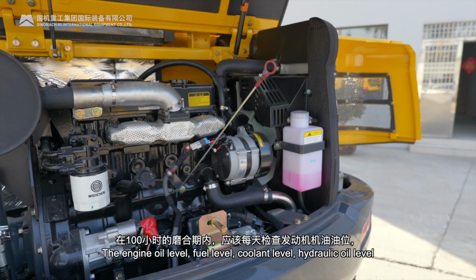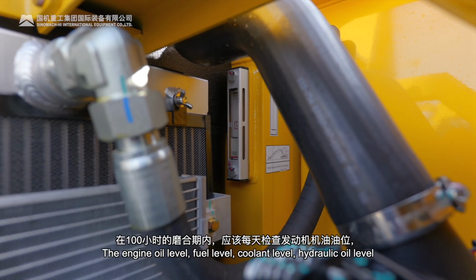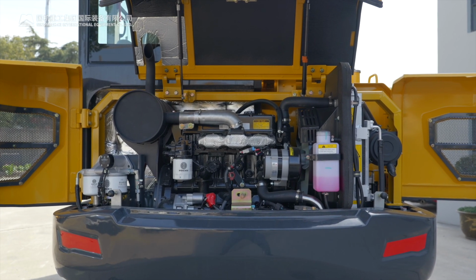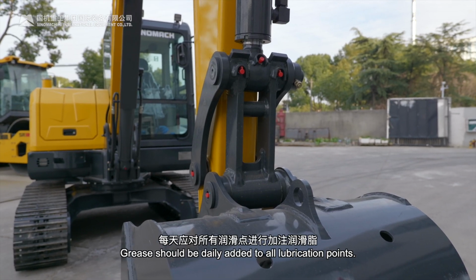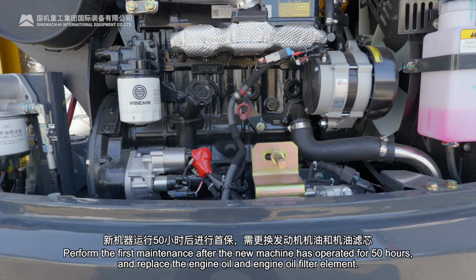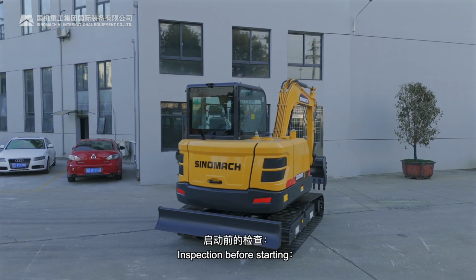The engine oil level, fuel level, coolant level, hydraulic oil level, and leakage situation should be checked daily during the 100-hour run-in period. Grease should be added daily to all lubrication points. Perform the first maintenance after the new machine has operated for 50 hours and replace the engine oil and engine oil filter element.